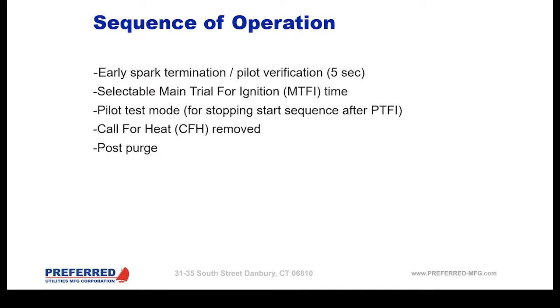And there are instances when the burner is designed right so that the scanner can't see its own spark, but if there's stainless steel inside the furnace, it can bounce the UV all around and back to the flame scanner. That can happen also, absolutely. Another reason to do early spark termination, and a nice thing to have as a selection on a flame safeguard. Some flame safeguards require you to change the programmer, and obviously in ours that's a selection.